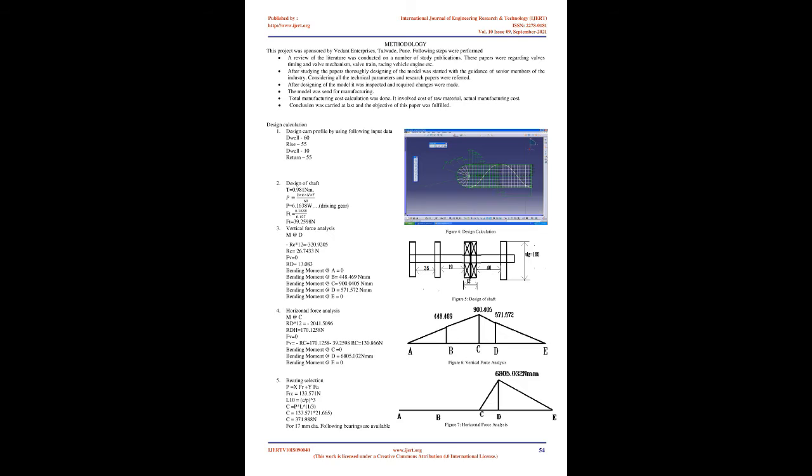The model includes a lumped parameter model for the moving camshafts, a finite element camshaft model, and a lumped parameter model for two cam valve systems, one per camshaft. The model validation process, based on the tests performed on the test bench described here, was presented and discussed. Comparisons between numerical results and test data show that model performance is satisfactory.